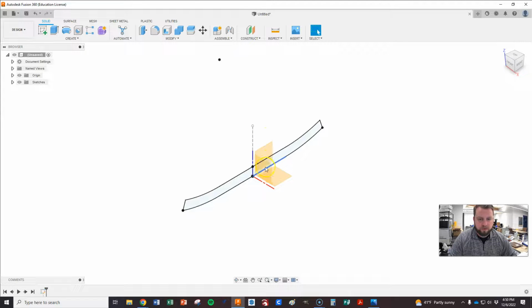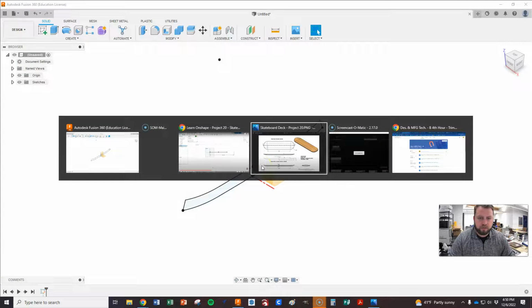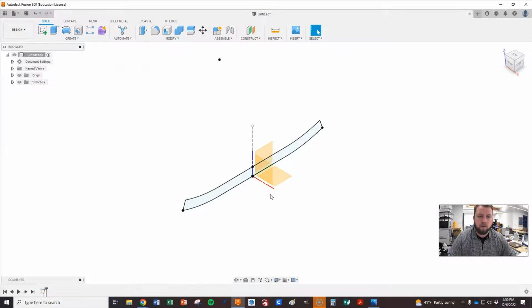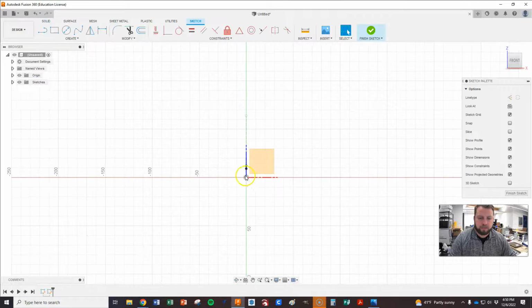And now we're going to create a new sketch, because what we need to do is draw what we see here. We're going to do it in the almost exact same fashion that we just did. We'll draw this one in the front view though. So we're going to go out, straight line 300, place a point that's out there 420 up. Alright, and we'll make that same tangent curve and all that good stuff. So straight 300, point at 420. Alright, so make sure that we get the front plane very carefully and right click it. Create a sketch.